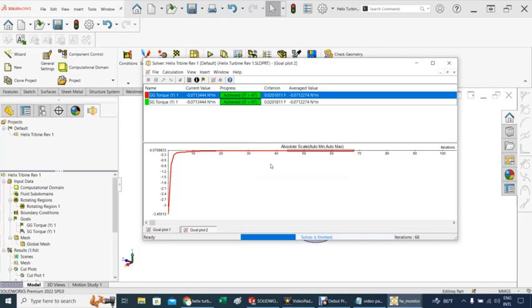Now, as you can see, I'm increasing the spinner RPM, and the value of the torque is getting smaller. But now you are extracting power because it's spinning. The problem is that if it doesn't spin, then you are not extracting power, because in this case, power is torque times RPM in radians per second. And that's the important thing about that. The spinner needs to spin in order for you to extract power.